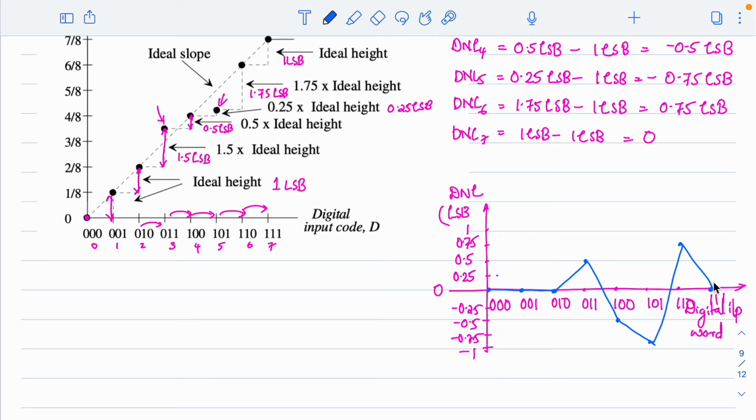and even from the table itself we can analyze, but it is a regular practice to plot it. Generally for a DAC to be n bit accurate, the maximum DNL for an n bit accurate DAC is considered as plus or minus half of an LSB.